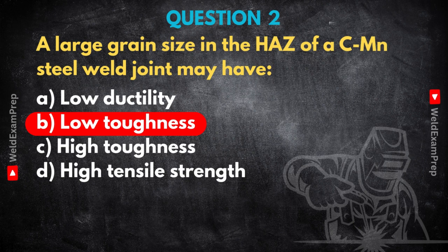Maybe ultrasonic testing or even destructive tests like Charpy impact tests on representative samples to directly measure the toughness. Okay. It really forces you to verify the actual properties, not just assume they're okay based on the welding procedure, especially if control was maybe a bit loose. Makes sense. You're looking beyond the surface.